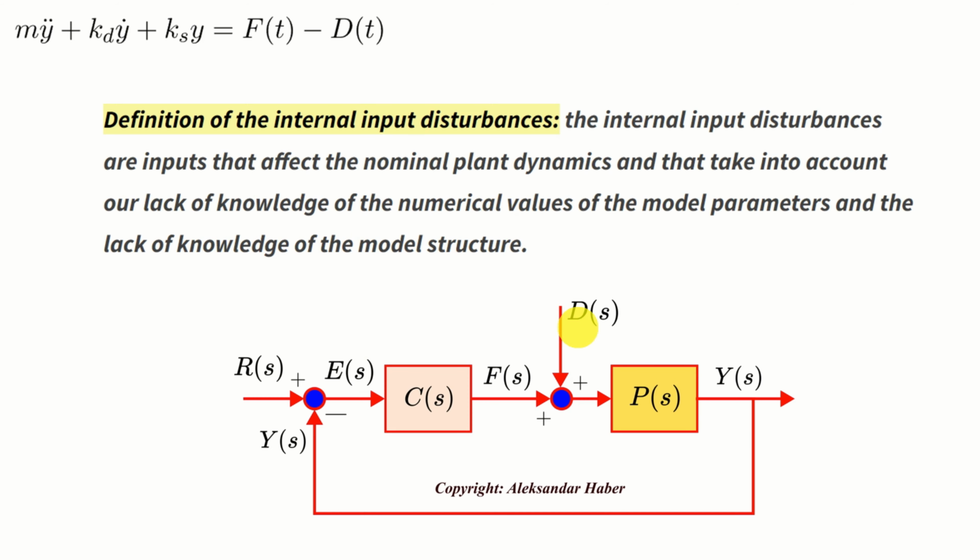To summarize and to define the internal input disturbances: the internal input disturbances are inputs that affect the nominal plant dynamics and that take into account our lack of knowledge of the numerical values of the model parameters and the lack of knowledge of the model structure.